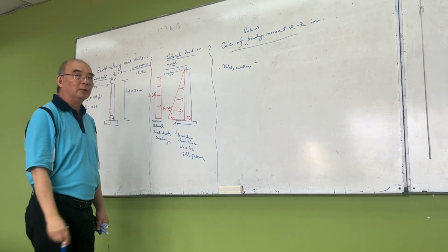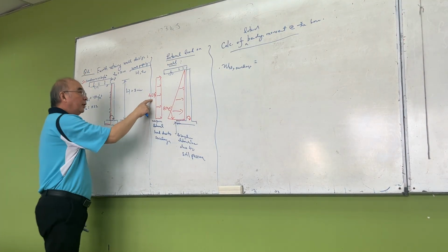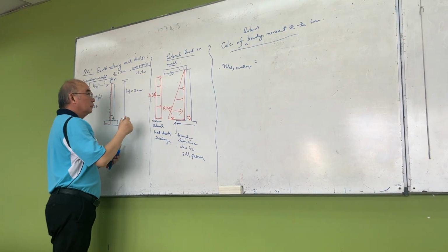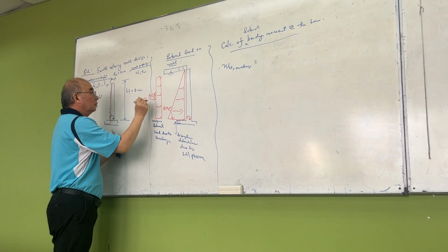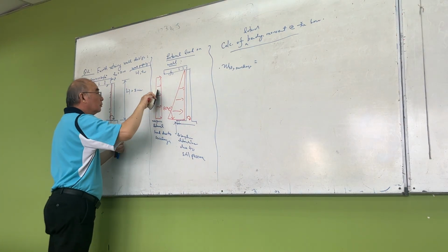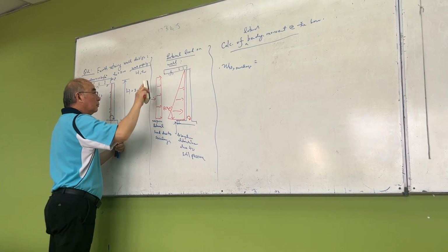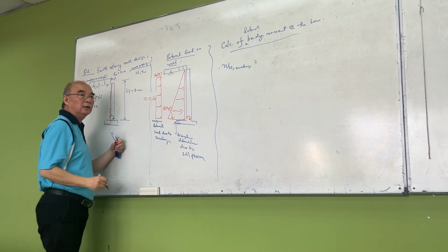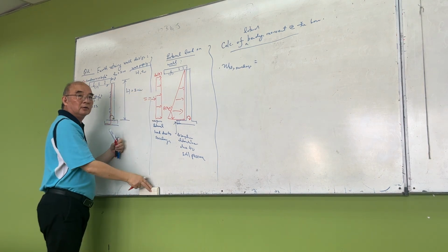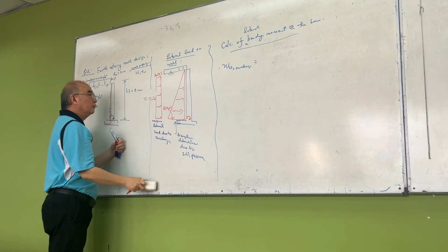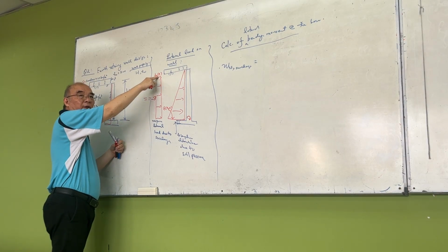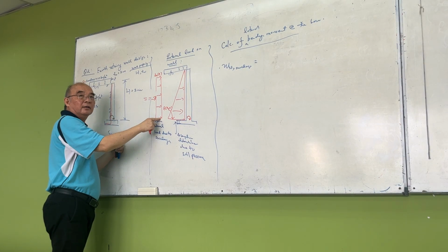Ms due to surcharge is what? Pressure multiplied by the height gives me the force. So this is Ka times surcharge, so this is the pressure. So the force is just this pressure multiplied by the height.